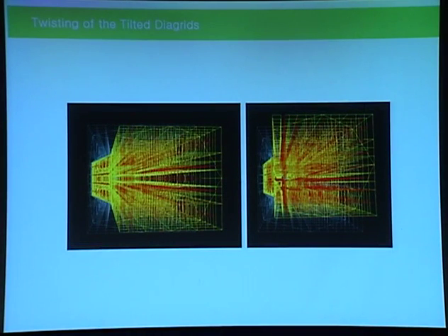And another consideration is that the previous graph was based upon the wind load parallel to the direction of the tilting. But if the wind load is coming from the direction perpendicular to the direction of the tilting, then based upon this eccentricity, this building gets twisted.